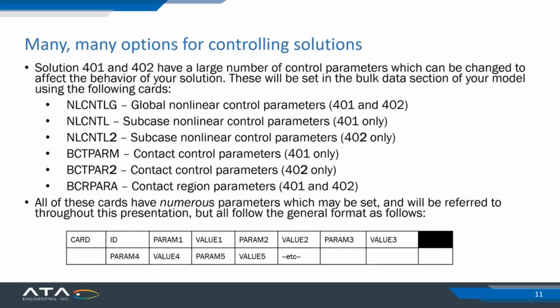And then lastly, when you are running solutions 401 and 402, because they're nonlinear solutions that converge, there are lots of control parameters which are available to you to be changed to control the solution behavior to get better convergence or to affect just the overall behavior of the solution. There's global nonlinear control parameters, which are applicable to solutions 401 and 402, and that's the NLCNTLG card. And then there are nonlinear control cards: there's one for 401 and one for 402.